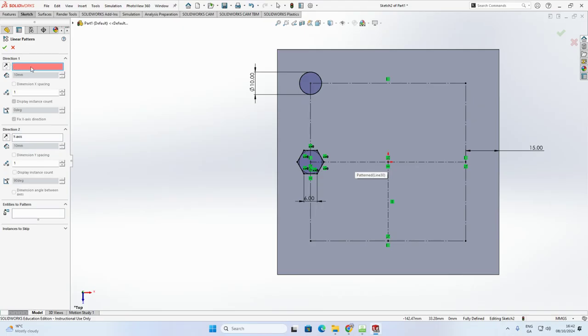It is now empty. So I need to fill this with something. The path I wanted to follow is this line here. So all I'm going to do is select this line and watch it will go in here. Click line 26 at sketch 2. Perfect. Now I want 3 circles. So here's my number. It's currently on 1. I'm going to go up 1, 2, 3.